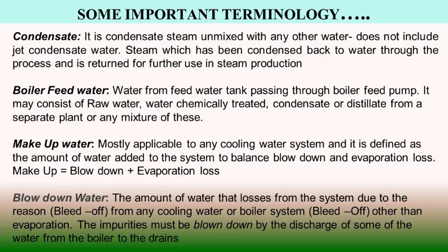Any mixture of different sources of water in the feed water storage tank can be called boiler feed water. Makeup water in any cooling water system is defined as the amount of water added to the system to balance the losses due to blowdown, leakages, drainage and evaporation. Makeup water is actually equal to blowdown losses, evaporation losses and drainage losses.